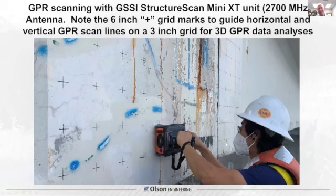So here we are scanning. In this case, we weren't trying to estimate the corrosion. That's more typically done on bridge decks. We were trying to locate the metal embedments. This particular unit is a higher frequency, 2700 megahertz, that has a screen built in, very convenient to use. And you just roll it along the concrete surface. You can see the 6-inch grid. So we were able to scan, in this case, we wanted to scan every 3 inches horizontally and then every 3 inches vertically, using the 6-inch grid as the guidance. And you can also see some of the cracks and other things showing up in this photograph.